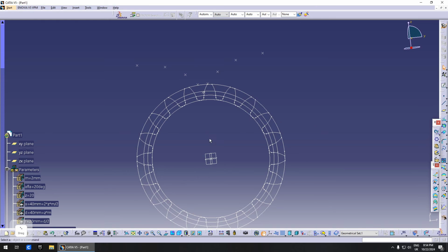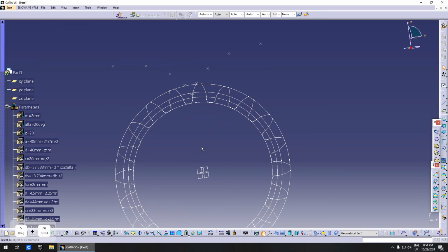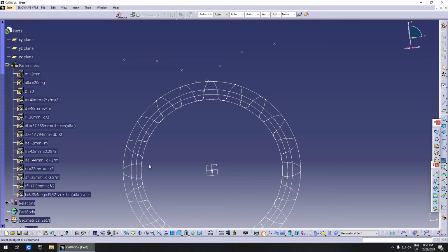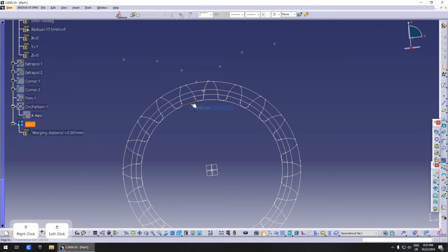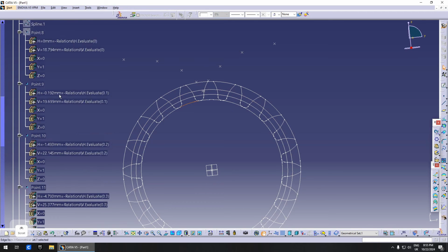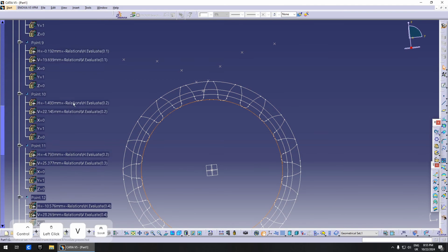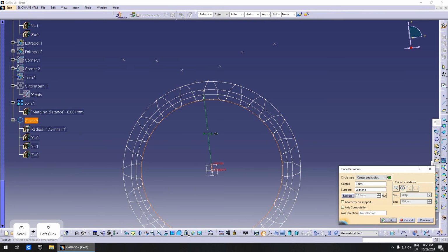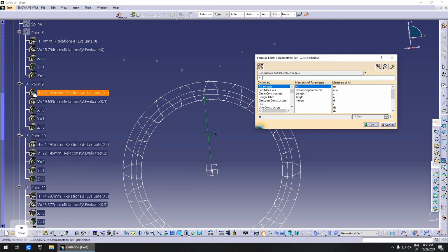What you have to do now is extrude them, or rather make a pad. Normally there's a little difference in thickness here, so I guess we need another circle which is connected to the base one. Which one is the base one? Let's see, this one. So we'll copy this. It's already linked, it already has the formula, this, but we need to make this slightly smaller. So how do we do that? We subtract.